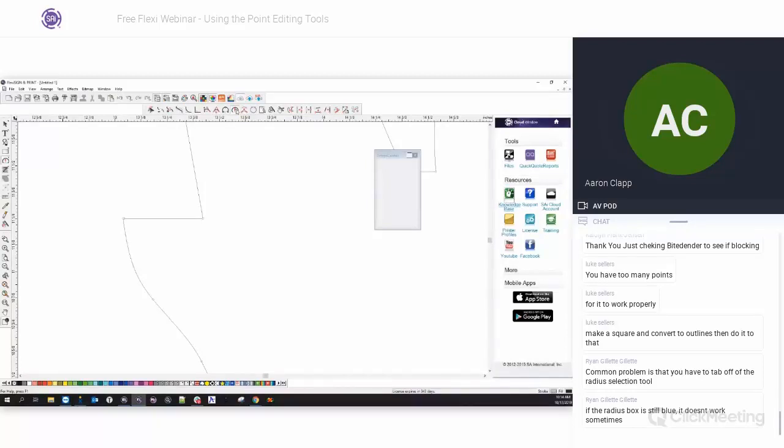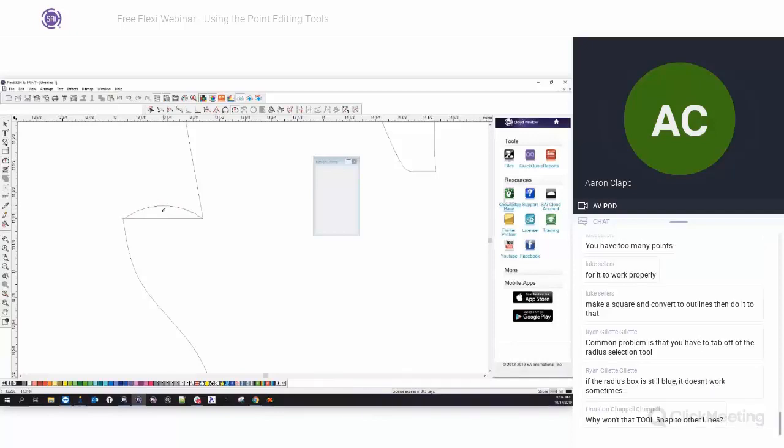This next arc tool up here is a kind of interesting one. It doesn't have any parameters. As you can see, Design Central is actually blank. There's nothing there. What this actually does, in this case, is it just gives you a special cursor and allows you to drag this line into an arc. So if it was a line before, I can just simply go up or down, and it doesn't have a whole lot of adjustment. So you're basically just editing the midpoint of this line and increasing it up or down.